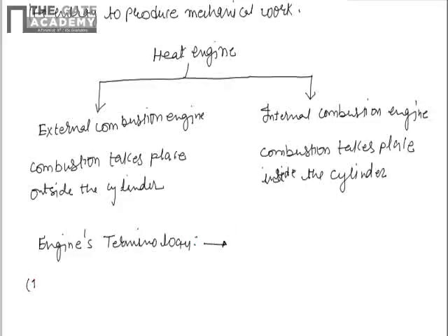First one is piston swept volume, which is denoted by Vs. Remember one thing, whenever in a problem some volume is mentioned without saying whether it is piston swept volume or total volume, by default it will be piston swept volume.